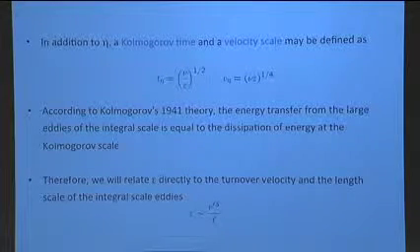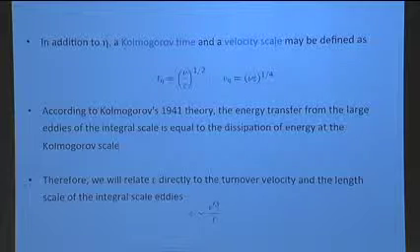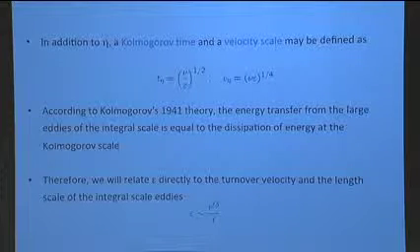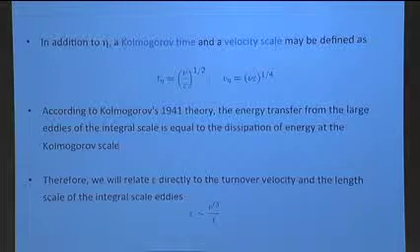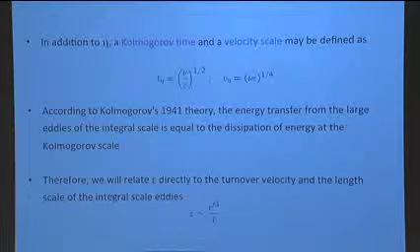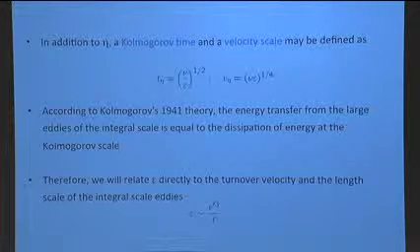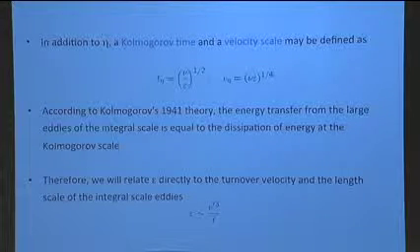Now, one thing that's interesting is, earlier I said there are two things really we learned from the Kolmogorov theory, or maybe three. The smallest scales of turbulence, that's one. The second was that there is this inertial subrange, where the kinetic energy depends only on epsilon and the wave number that you're looking at. And the third, that is very important, is the so-called Kolmogorov scaling.